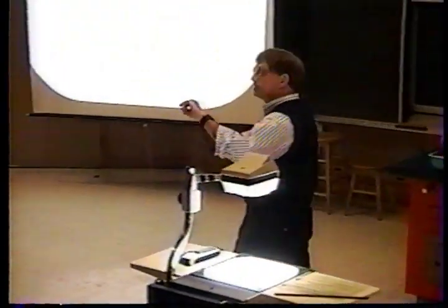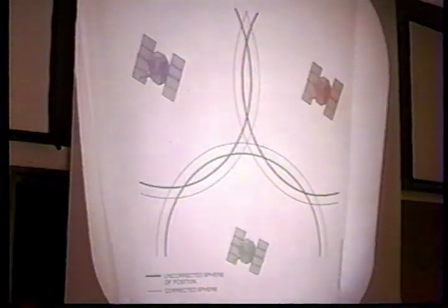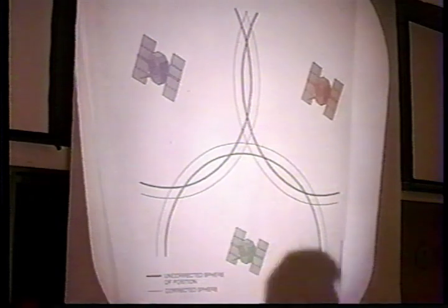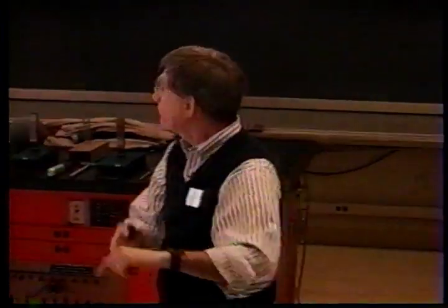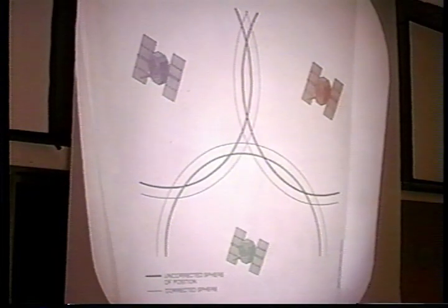The way the GPS system deals with that problem is that you use a third satellite at another known location, the green one. So you measure the pseudo range here, a solid green line. It intersects at 2 points here, and up here at 2 points. So I got 1, 2, 3, 4, 5, 6 intersections, and none of them are right because of my clock error. But it's the same clock error. There's one delta t. It's my clock that's at fault. So I just start adjusting it by trial and error. And there's one value of delta t which brings this into a triple coincidence right here.